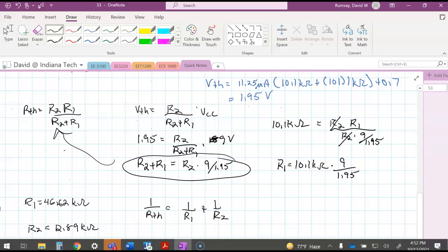so you're going to have to do some approximating. But we do have like a 47k ohm resistor, and we do have like a 12k ohm resistor. Is that going to affect where your load line position is? Absolutely. So I would do your design, but then before you simulate, don't simulate this as your thing, because you want to simulate at least what it is you're going to actually use to build the circuit. Okay, so that's essentially what you're going to have to do for your design portion,